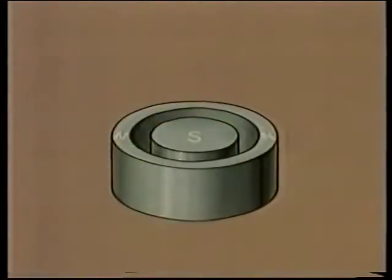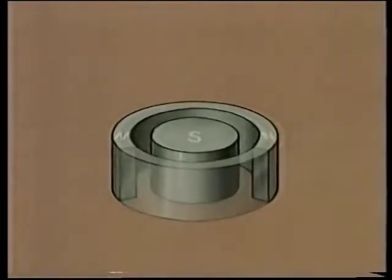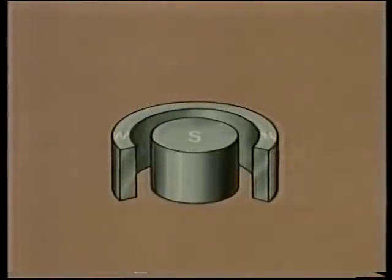Okay, now let's look at a simplified representation of this drive unit so that we can understand how it works. The magnet assembly is circular, with, say, a central south pole surrounded by an annular north pole. Now, removing the front of the magnet will help to make things clearer. The magnetic flux lines are radially directed from the north to south poles.